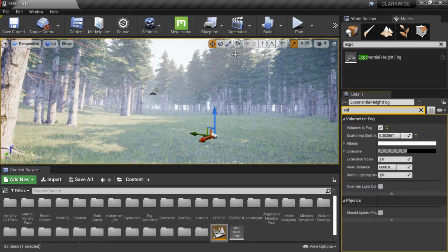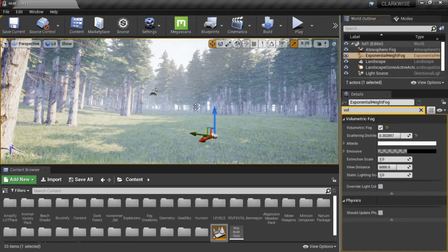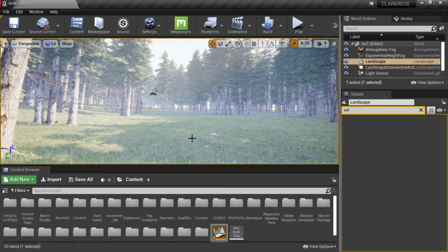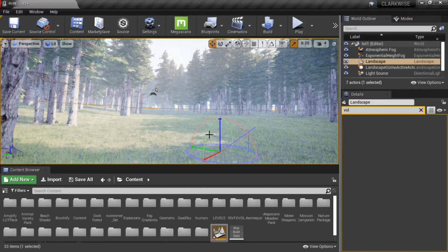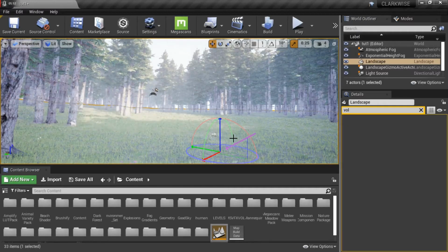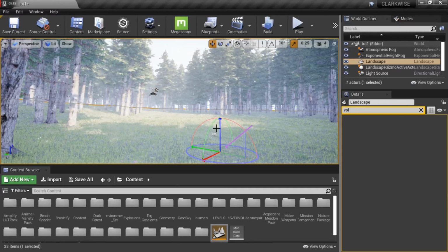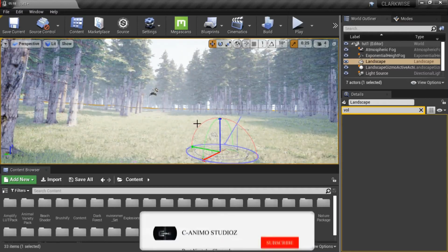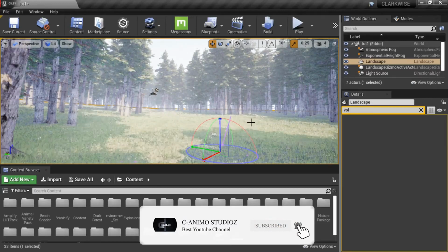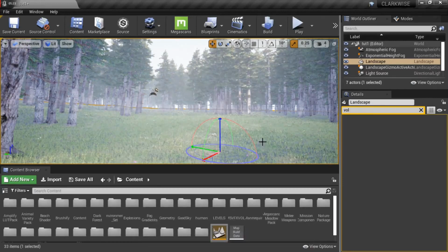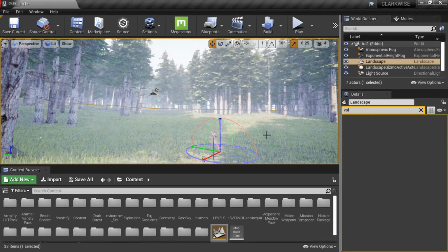So to actually work on this, I need to position the sun. If the light is going to pass through the trees to get me some nice God rays, what you're going to do is click on the landscape itself and press Control Alt L, and you see this gizmo coming in here, and I need to choose a nice part that's going to give me some nice lighting around here. So that's nice and cool, but I need something better.